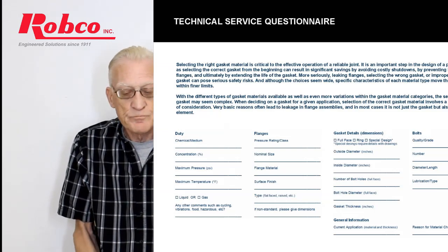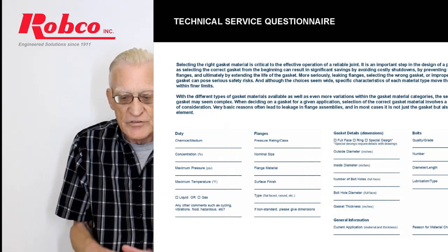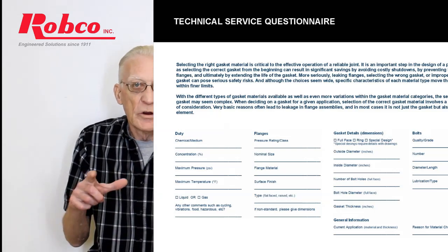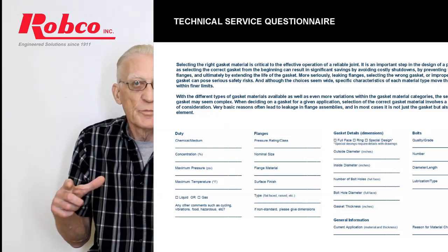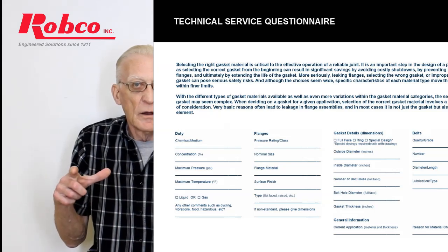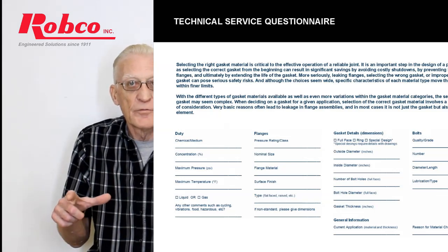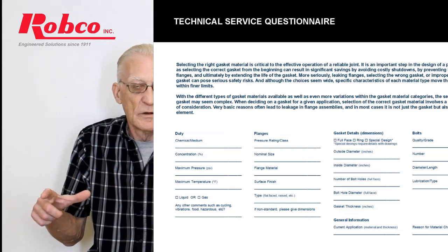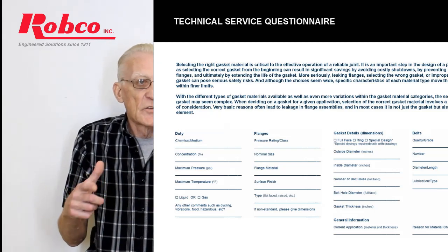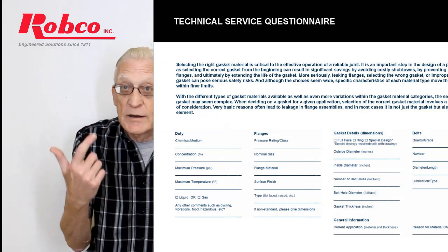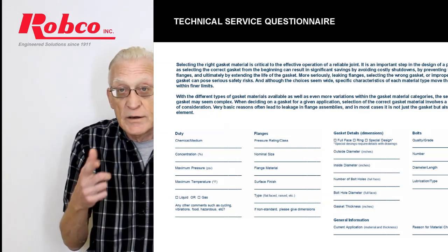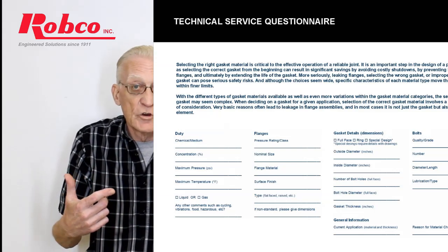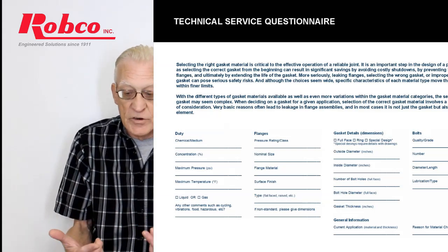An example, and we're going to get into sealing stress in a minute versus area, but maybe your gasket's too wide, which means that you have too much gasket to compress and not enough load to compress that much area. We'll understand that in a sec, except to say that maybe I need to add a bolt, maybe I need to redesign and put more bolts in or take bolts out because I had too much load, etc.